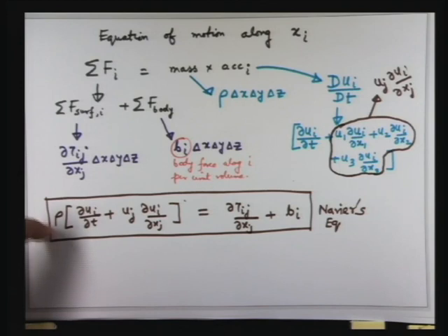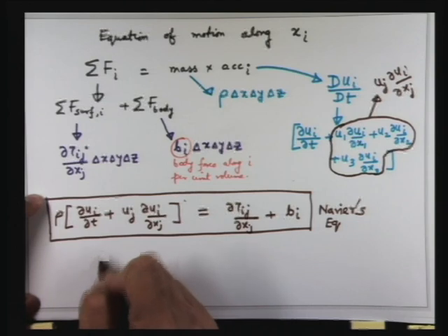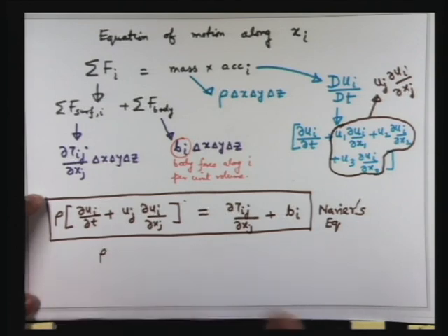So in terms of fluid flow, how many equations are there? 3 components of this equation plus the continuity equation. So 4 equations. How many unknowns are there? So let us identify the unknowns. In general, rho may be an unknown, rho may be known also, but rho also may be unknown. So rho,